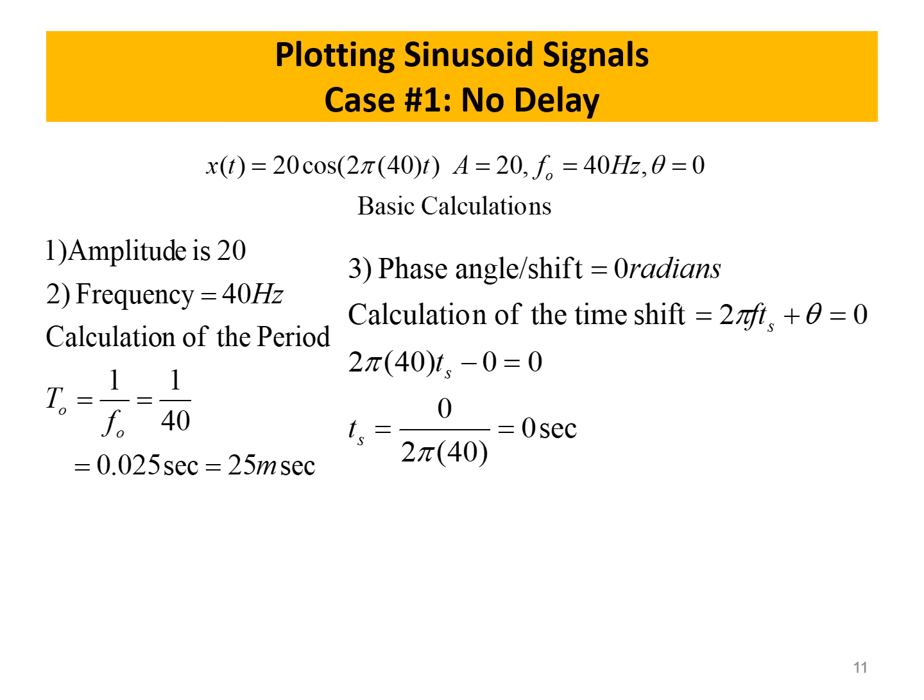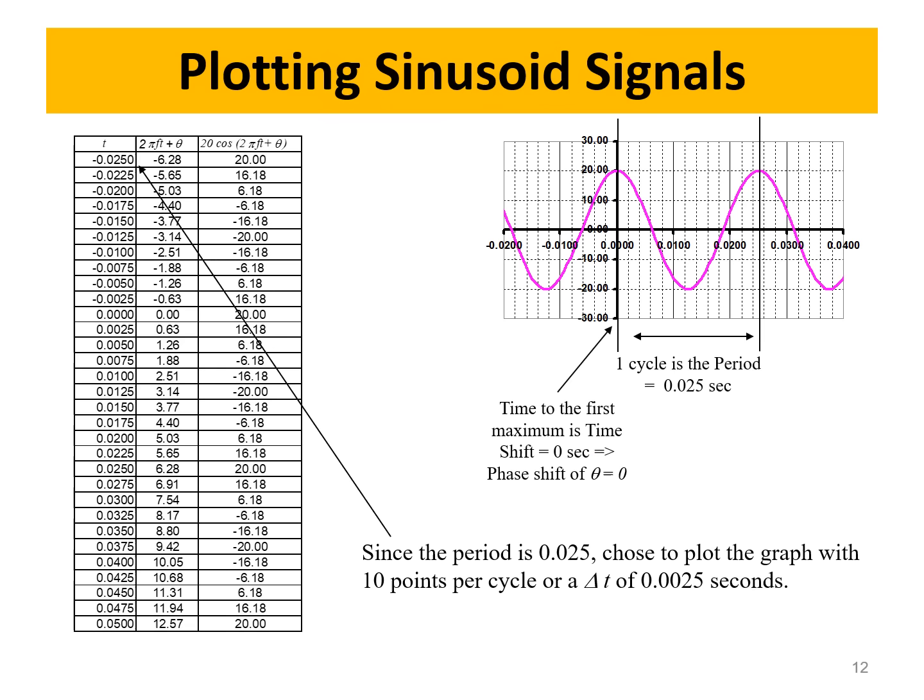This is another example, and again, we don't have any phase shift because the whole thing is without phi, so the angle is without a phase shift. You can calculate the amplitude, the frequency, the period. The phase shift is 0, right? We don't have any phase shift. And then you can calculate the time shift. You put 0 on the top, as I mentioned, the phi, and then you divide it by the radian frequency, and it's 0 points. So when you plot it, it starts here, at the top. But you need to know the period and all the other information so you can plot your signal.